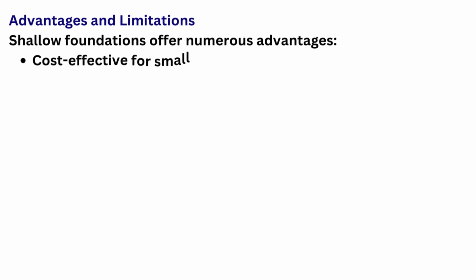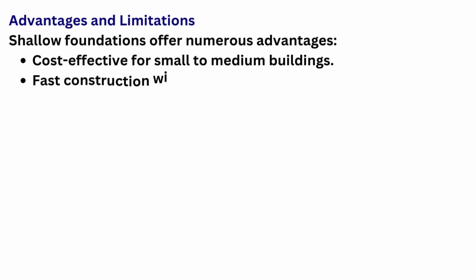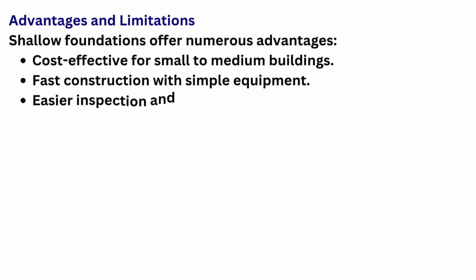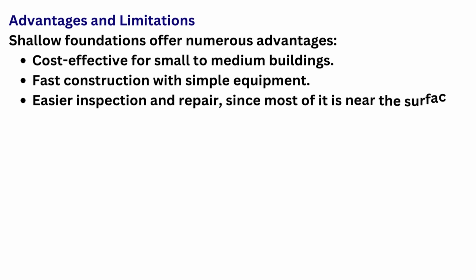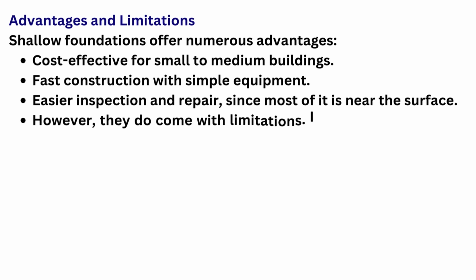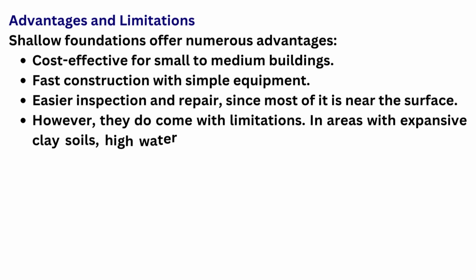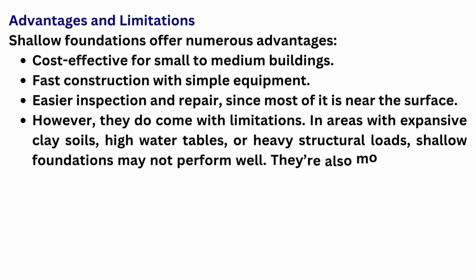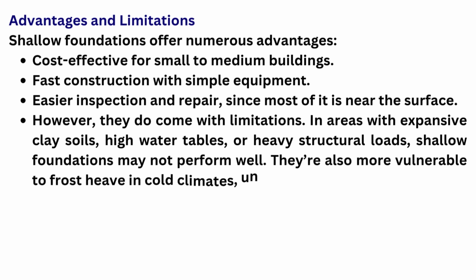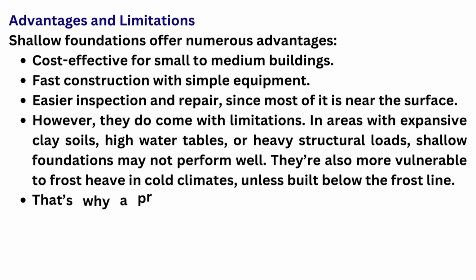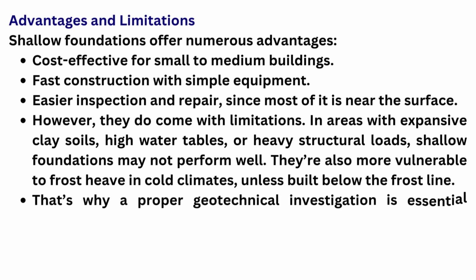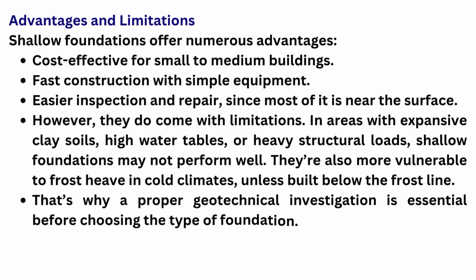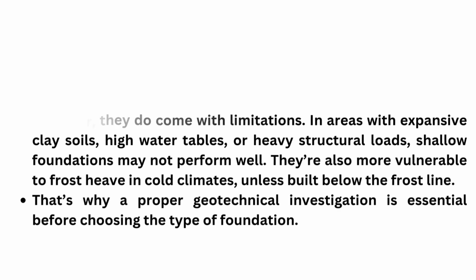Advantages and limitations. Shallow foundations offer numerous advantages. They are cost-effective for small to medium buildings. Fast construction with simple equipment. Easier inspection and repair, since most of it is near the surface. However, they do come with limitations. In areas with expansive clay soils, high water tables, or heavy structural loads, shallow foundations may not perform well. They're also more vulnerable to frost heave in cold climates, unless built below the frost line. That's why a proper geotechnical investigation is essential before choosing the type of foundation.